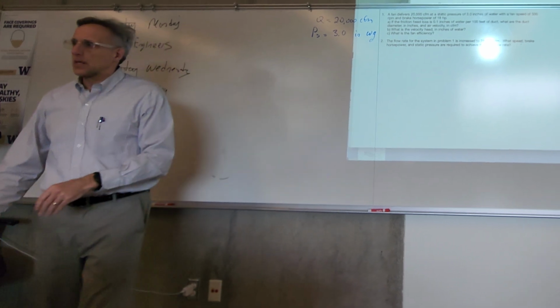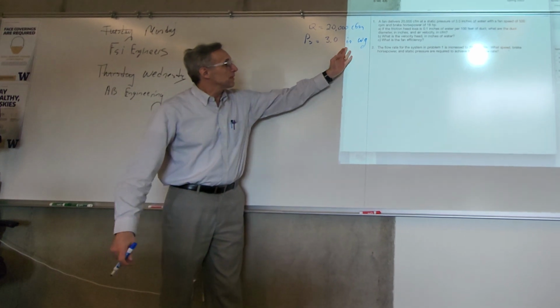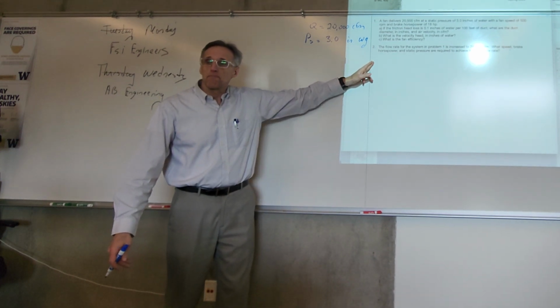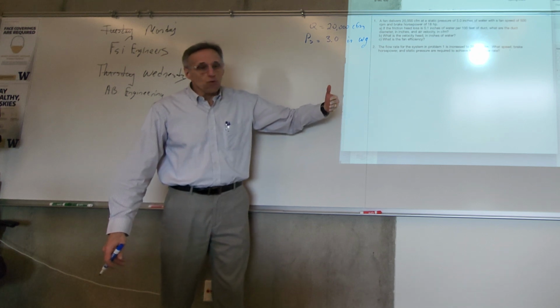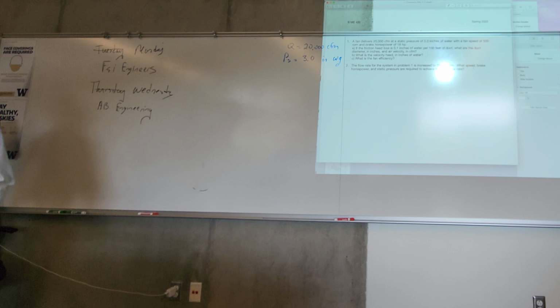This is a conventional abbreviation for pressure: inches of water gauge. When you talk about inches of water, it's almost always a gauge pressure, so it's relative to atmospheric pressure.